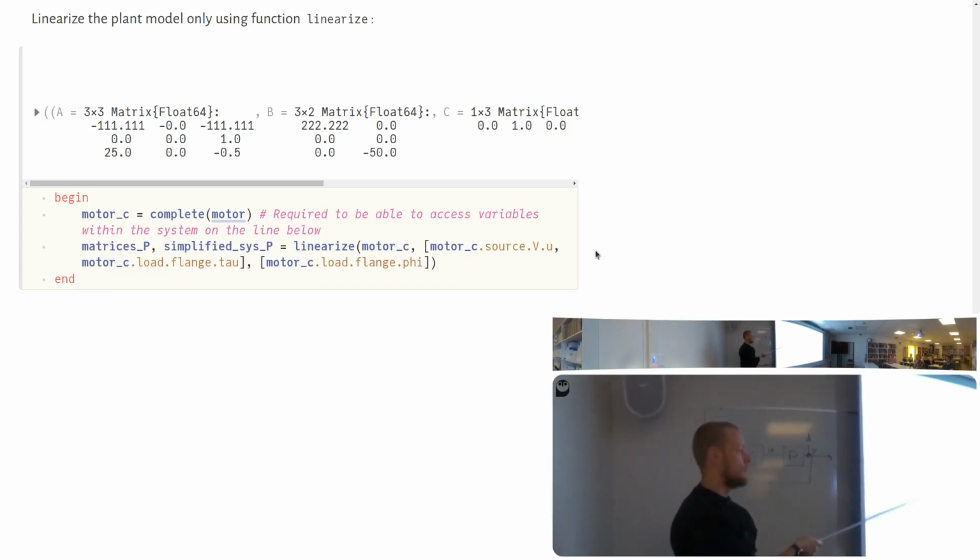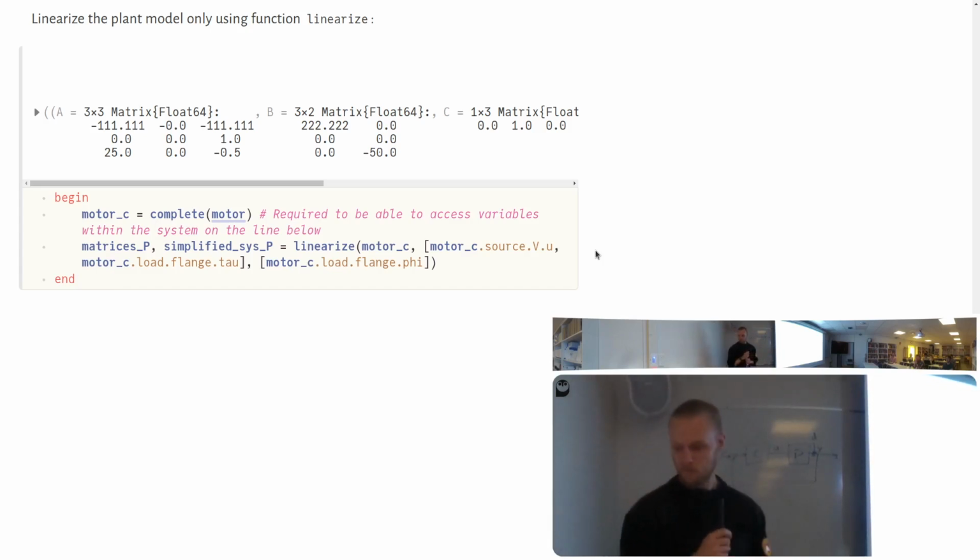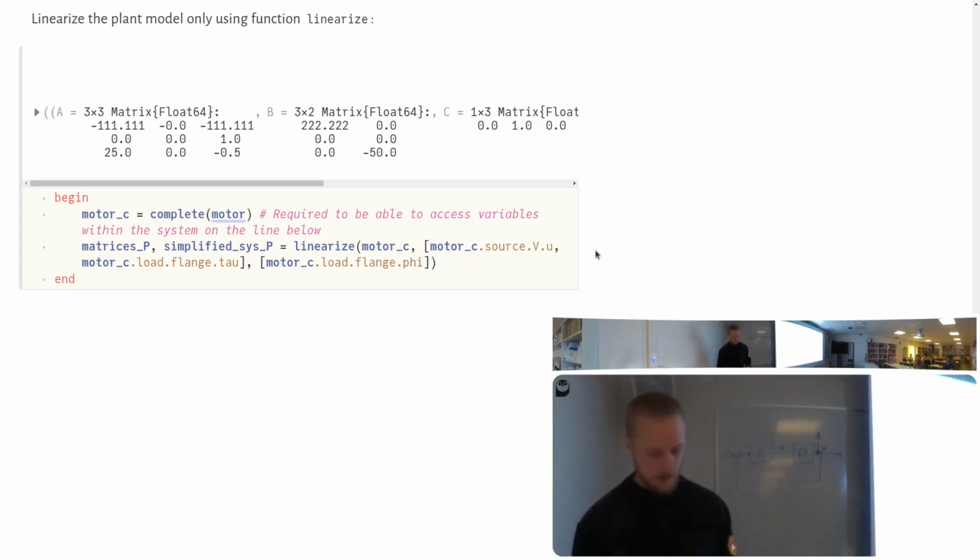You can also do frequency response analysis. So we do that in practice maybe if we want to estimate the model of our system. We send sinusoidal signals in there, or a chirp, something like that. We can do that in simulation also, and that will give us a linear model. So all of that is feasible to do.